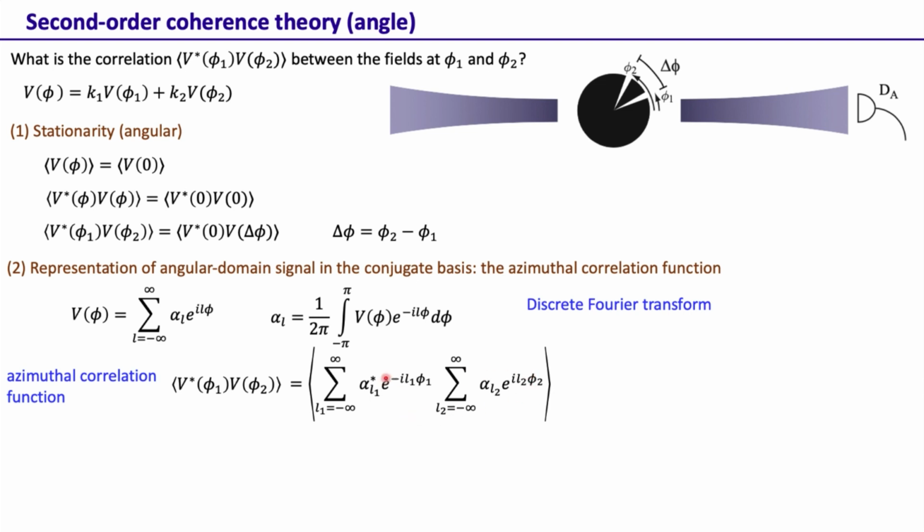Okay. Now again, in all of this, the only random quantity are these alpha. Again, let me mention it here. When we write this for a random signal, this is more of a symbolic thing, because if this is V phi, since a continuous Fourier transform cannot exist, similarly the discrete Fourier transform also cannot exist. So this at this point is in a symbolic form, but when we calculate the correlation, that's when it assumes a physical meaning, a concrete physical meaning.